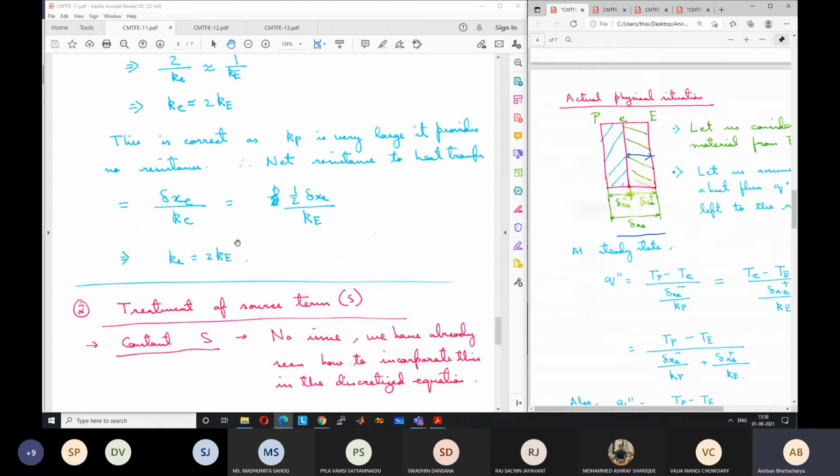So to summarize this point, in many cases, linear average will work, and we take the linear average in many cases. But it is always better and on the safe side to take the harmonic mean for all cases, because there may be a sudden jump at the interface, say I have metal on one side. Many of us are working in phase change materials. Phase change materials have low thermal conductivity, and we put some metallic films or foam, or a metal shell, to increase the average thermal conductivity.